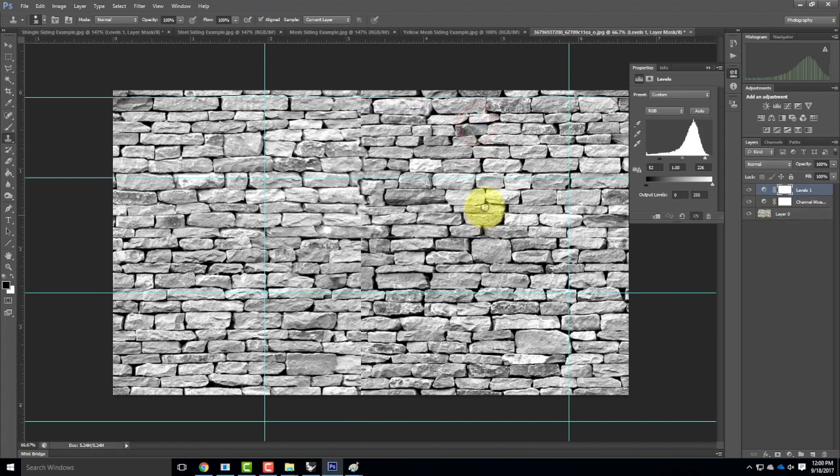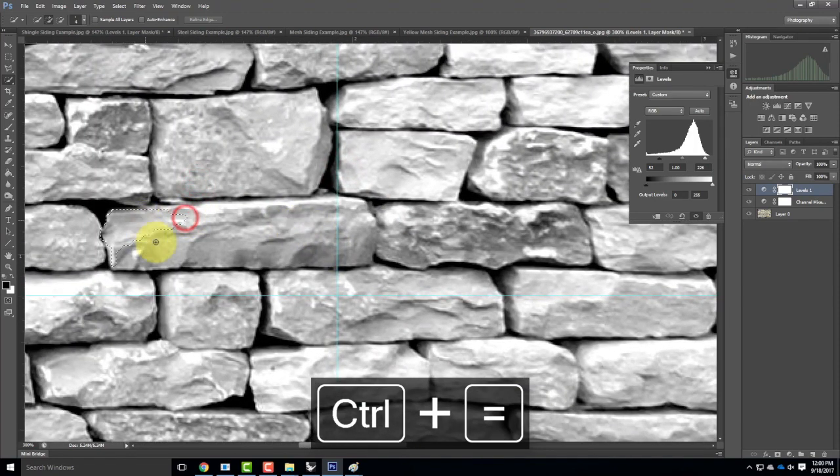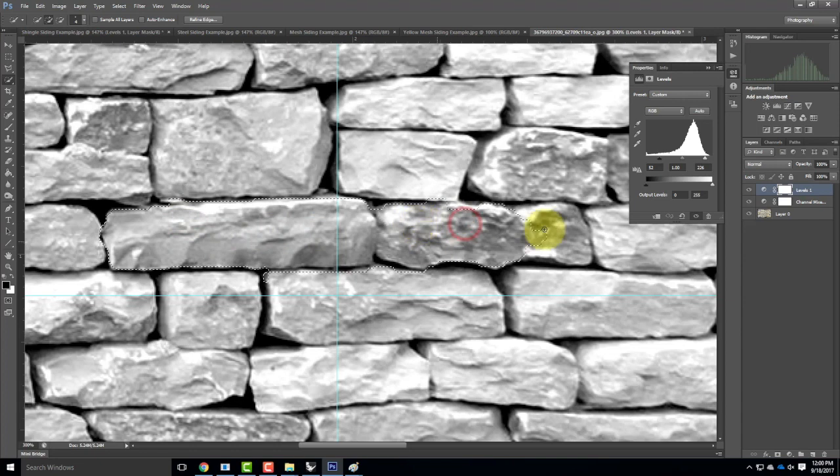Now when we get to the displacement map, we've got some deep grooves that are the black areas, but the white areas or the faces of the stones are all out a little bit. But there's also a lot of stones. So I can do this in a variety of ways. One, I could go in and actually select each individual stone. So I could come in here with maybe the quick selection tool, and I could start selecting the faces of each stone, not selecting the blacks, giving myself these grooves, and then I'm painting these in white and leaving the cracks in black.